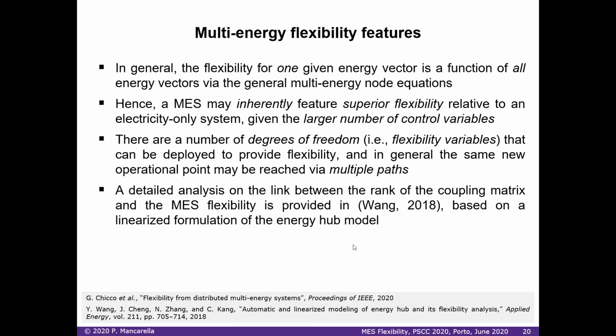There's also a very interesting paper that I would invite you to read by Wang and others from Professor Kang's research team at Tsinghua University, where they show with the methodology how you can have a linearized formulation of the energy hub, and then by looking at the matrix properties, particularly the ranks of matrices associated with the hub formulation, you can define some flexibility features in terms of degrees of freedom, which I've just mentioned. So there is actually a mathematical way of describing this. I invite you to have a look at the paper.